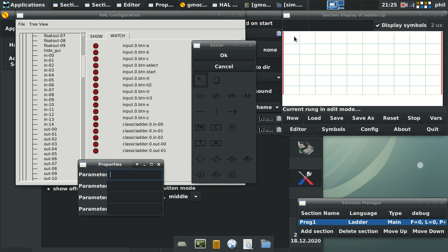Again, if you have a lube pump that is on a timer for 10 seconds and then shuts off for 10 minutes, you would build that in PLC logic instead of having to order timers, relays, things like that off of Amazon or the usual suspects and physically mount them into an electrical cabinet. This circumvents some of your physical hardware in exchange for virtual hardware. You create virtual input signals, virtual relay signals, and virtual outputs, and have timers and counters in between to perform various tasks.